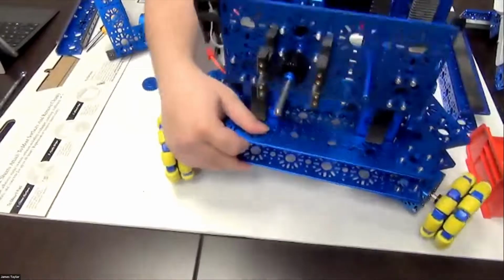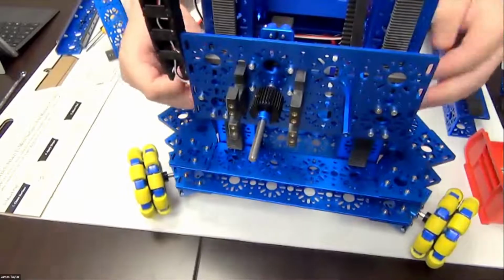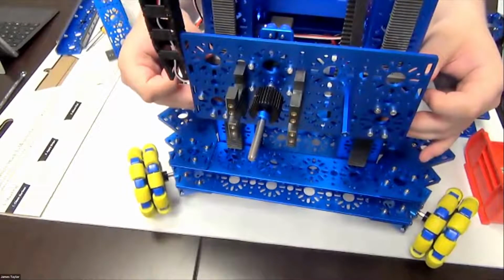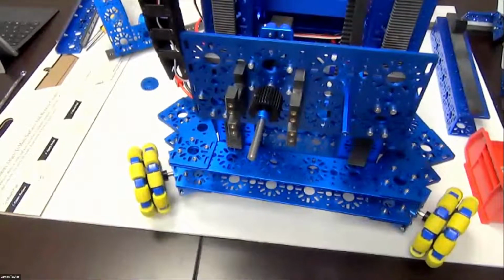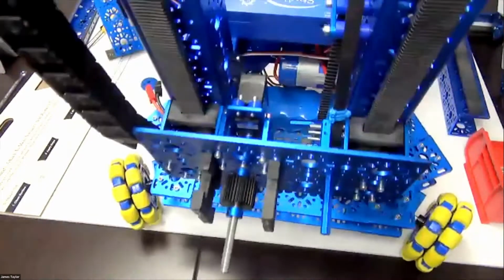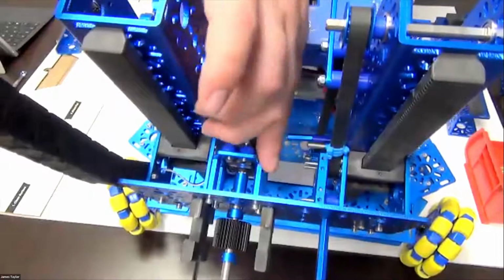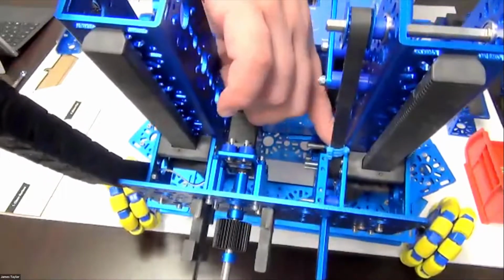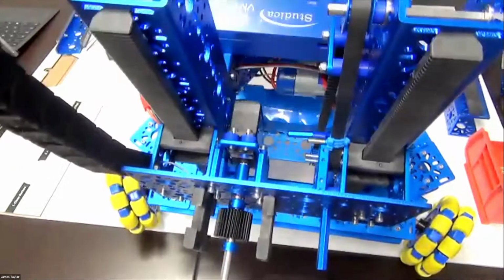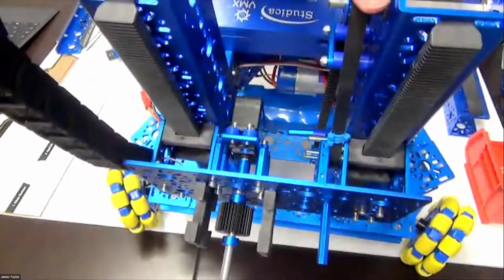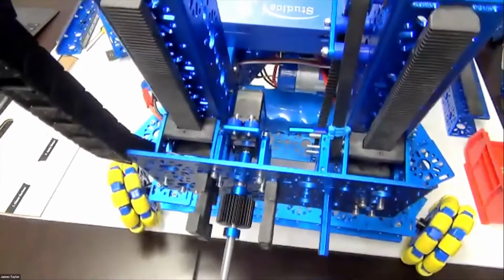The robot here, we have a flat plate that attaches to the two 48mm channels on the elevator. I'm not sure how well you can see that, so I'm going to tilt it. There you go. So we have the two 48 channels that have the rack and pinion glides on it. There is no pinion gear, as the elevator is not driven by a pinion gear. It's driven by that DC motor and the belt drive, which is here. And here you can see I created a little tensioner which pushes out to provide tension to the belt.